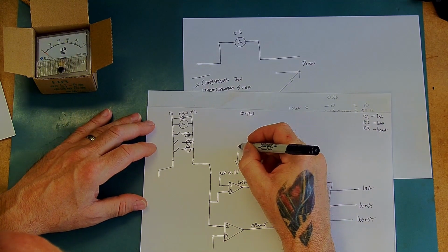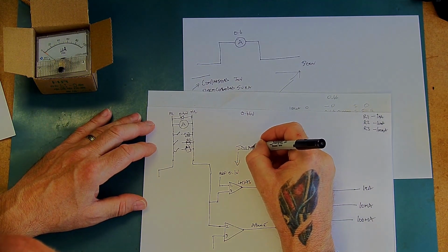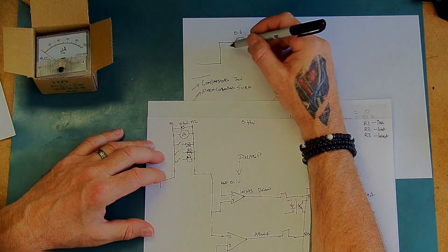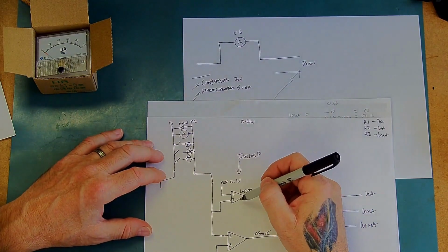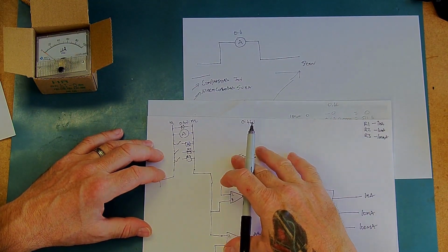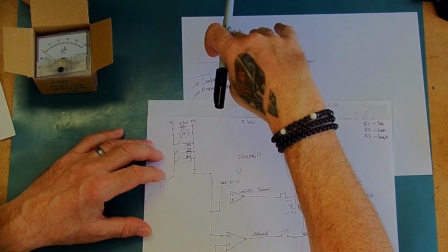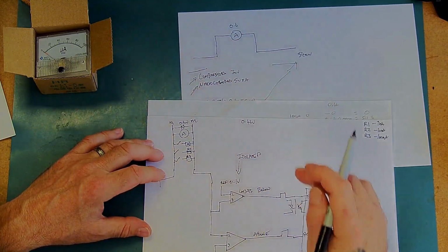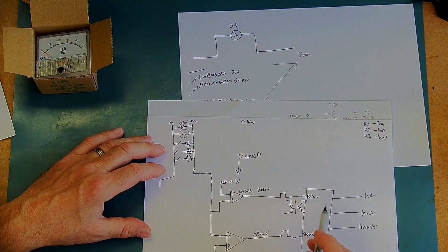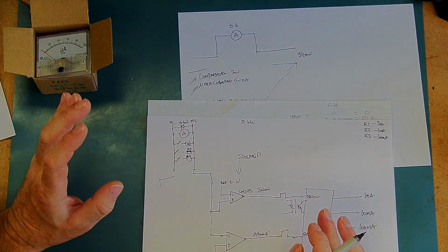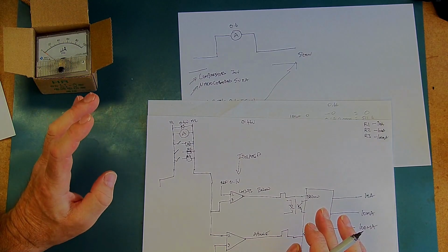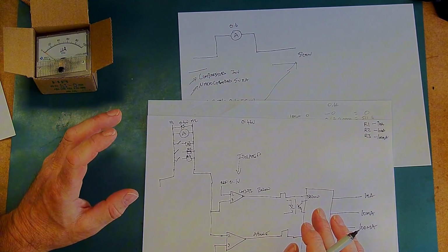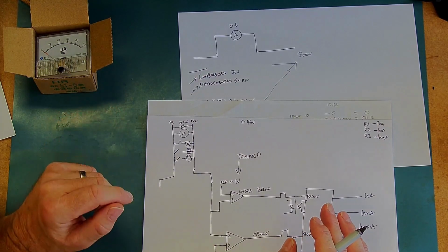and then I could have the actual supply for this isolated, and that way we can literally measure across the ammeter into the comparators, which will have an isolated supply, so they'll literally be measuring the voltage across the comparator rather than with reference to the ground potential, and then opto-isolate the inputs to that. So that's kind of what I'm thinking. But at this point I really don't know how I'm going to achieve that exactly, so that is the next stage for me. So in the next section of the video I've hopefully worked that out and have something else to show you.